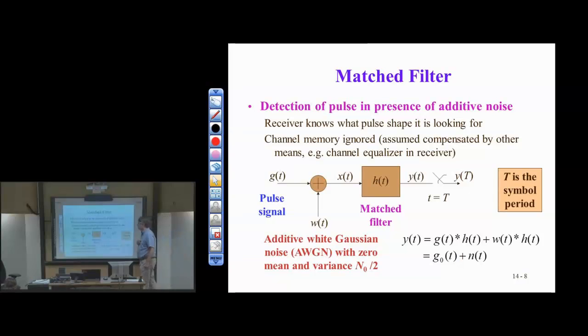And really, this is a more general story. It's not just communication systems. We use match filtering in lots of scenarios: ultrasound, sonar, radar. Very common technique. And the idea is to detect a pulse that we know embedded in noise. Very common problem in detection. And again, yes, there's a communication system application.